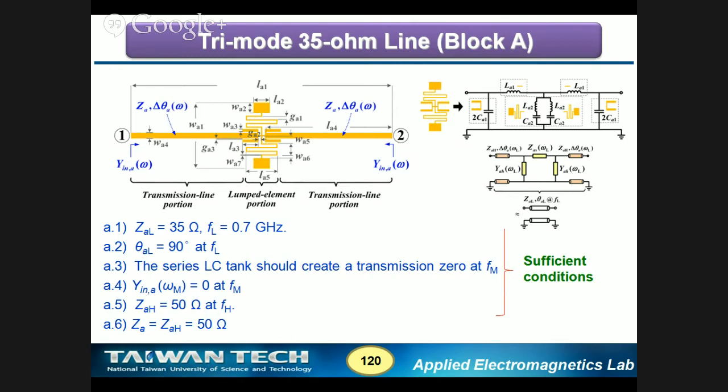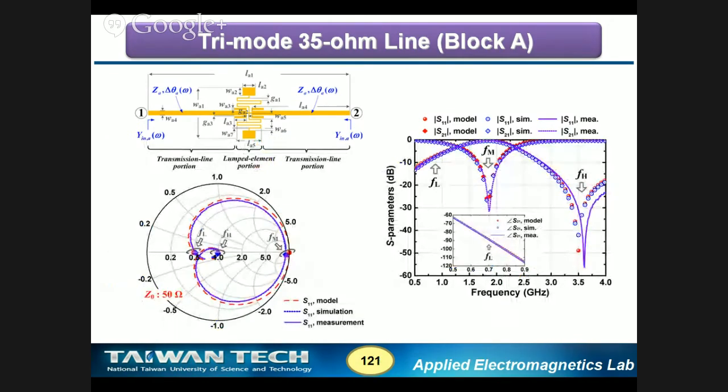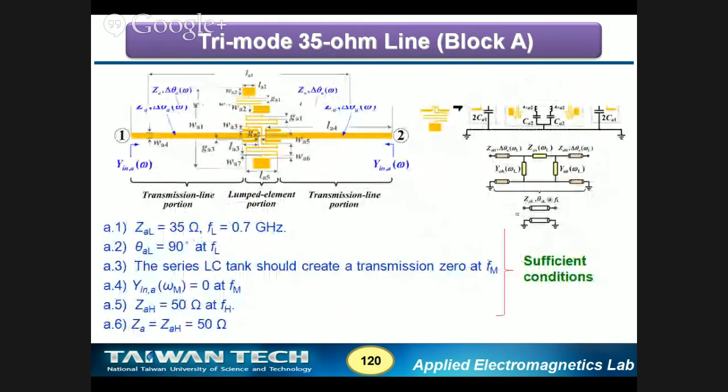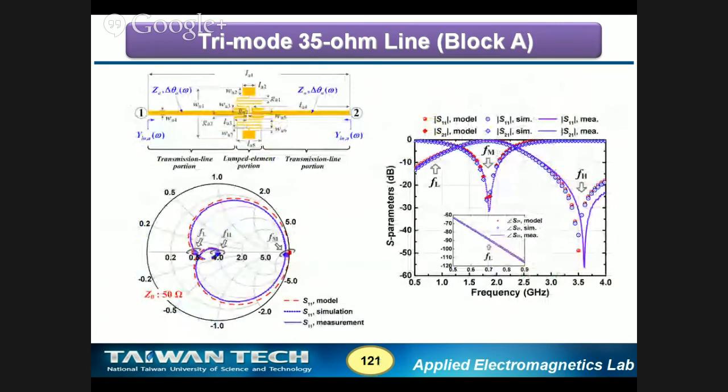We can uniquely solve using Mathematica. Indeed, we solved it using Mathematica, and we substituted back into a circuit emulator and checked its response. The response was somewhat like this. There are 3 curves here: modeled, using this non-modeled, the full-wave simulated, and the measurement.